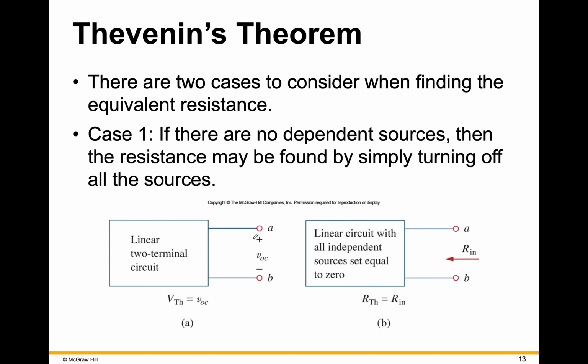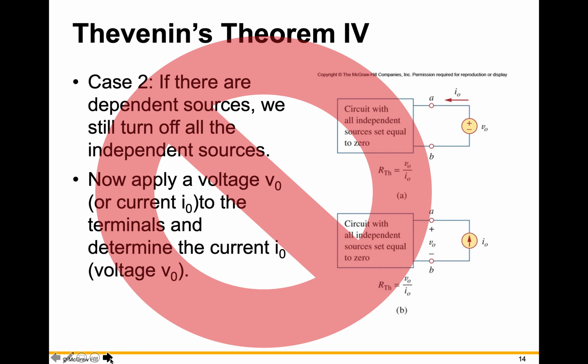And the Thevenin voltage is found just by finding what the open circuit voltage is. That's usually most easily accomplished using the node voltage method. So if you didn't like the node voltage method, most of the time, it's going to be significantly easier to use than mesh current.